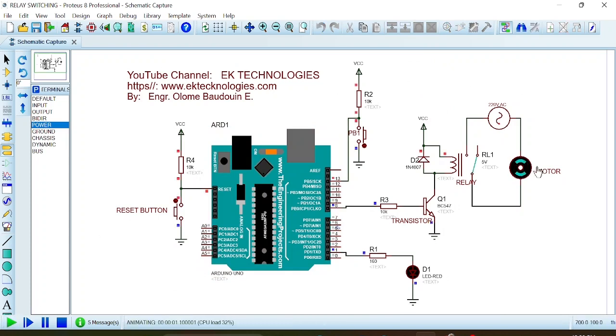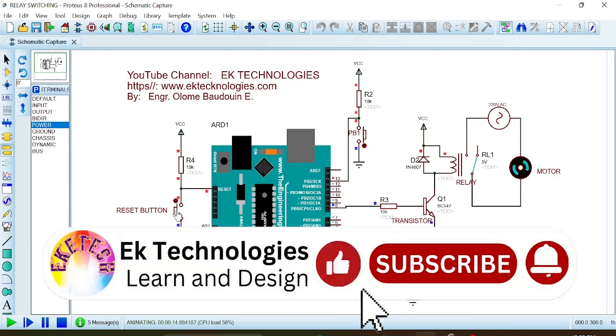So you see it is normally off. When we press, the motor comes on. You'll see the relay switching from this contact to this contact. You can reset the microcontroller by pressing the reset button here. You see everything stops. The microcontroller starts back and you can press the start push button. It turns on the motor. You can stop or reset here. So you have seen how you can interface a relay.